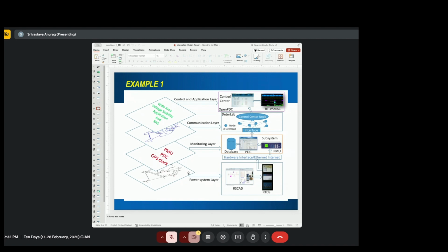If I use the steady state behavior model, it will not represent the PMU, basically the CT and PT current that is needed by the PMU. And then the PMU itself has so many different blocks, right? In the PMU, starting from the CT and PT, you have to first eliminate the noise, then you have to filter it. And then the filtering is done twice.